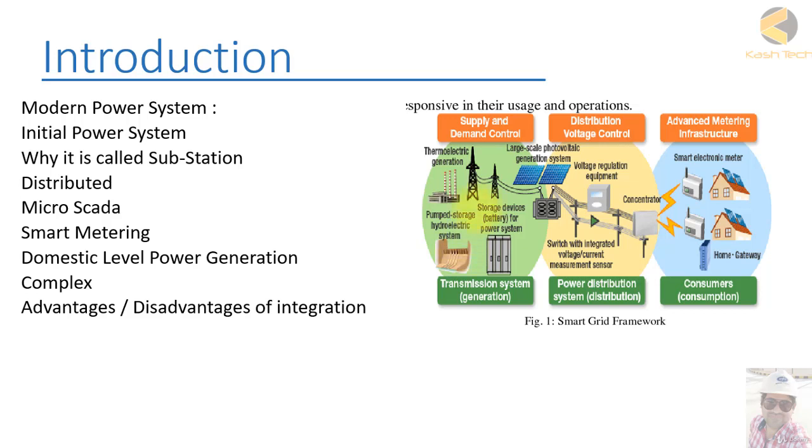The sending end HVDC substation is LCC, whereas the receiving end has two VSC substations. So this is one of the very unique and also rare combinations. Power control will be done especially at the LCC end.